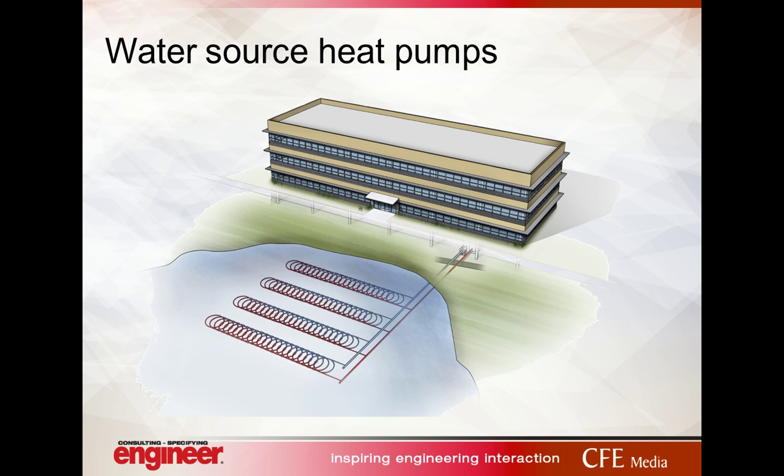Now, depending on how these are set up, you could run into that local recirculation limitation Jeremy talked about. They do have their own individual filters and compressors that would be above the ceiling or in the mechanical room, wherever they're at, and they could serve multiple spaces. But if they were coupled to a single room, you would potentially run into that local recirculation limitation.